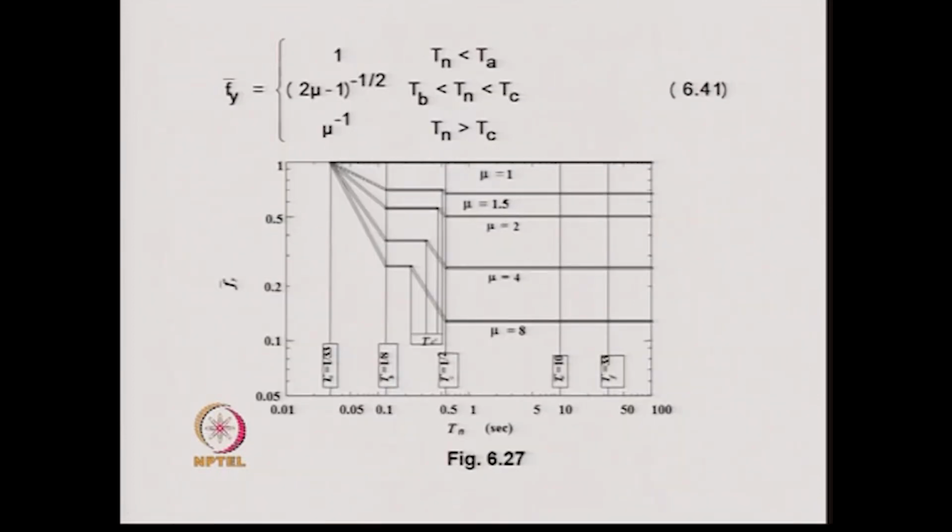Now, that effort of finding the curves for different earthquakes and idealizing them as a smooth curve led to a certain formulation of f bar y, or an equation for f bar y as a function of the ductility factor, which is valid for different time periods.